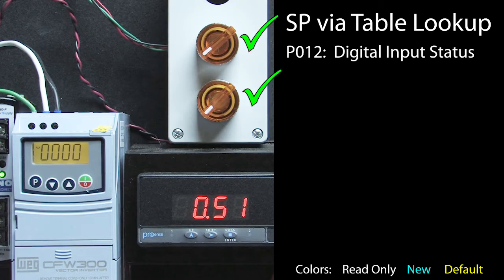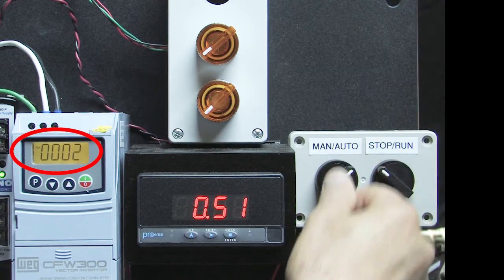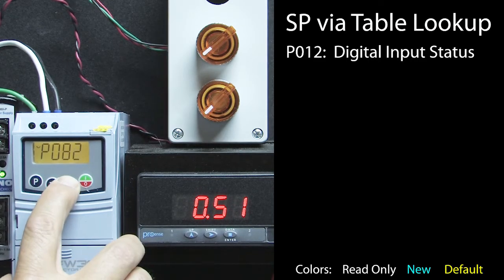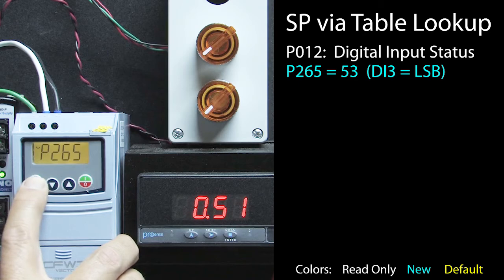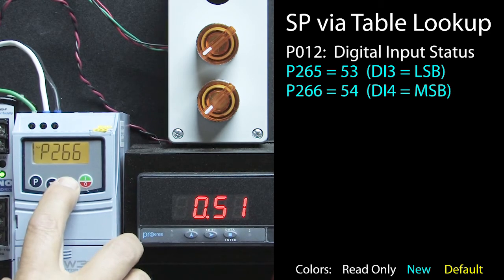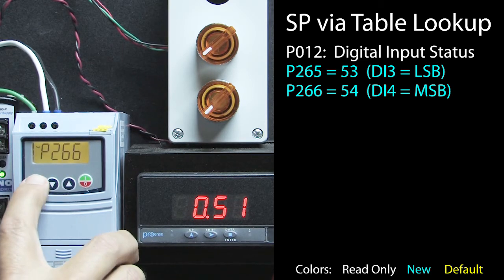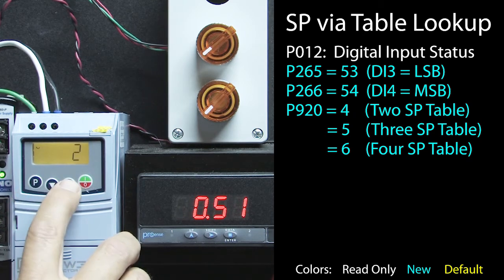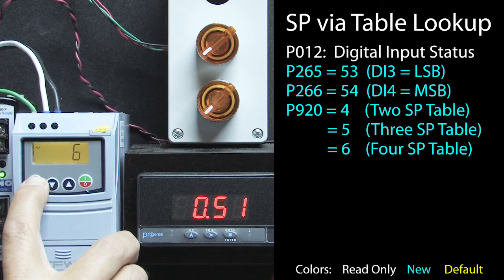I'll turn both switches back off and enable auto mode so PID automatically controls the motor when we switch to run. Let's go to parameter 265 to tell digital input 3 he'll be the least significant bit of our selector, and parameter 266 to tell digital input 4 he'll be the most significant bit of the selector. And let's go back to parameter 920 to tell the PID application to use digital inputs 3 and 4 to select the set point values from a table.